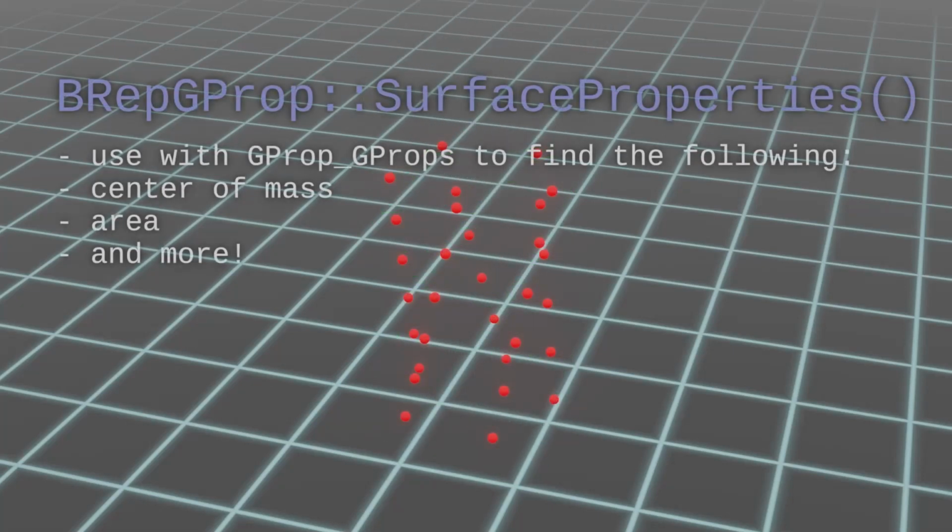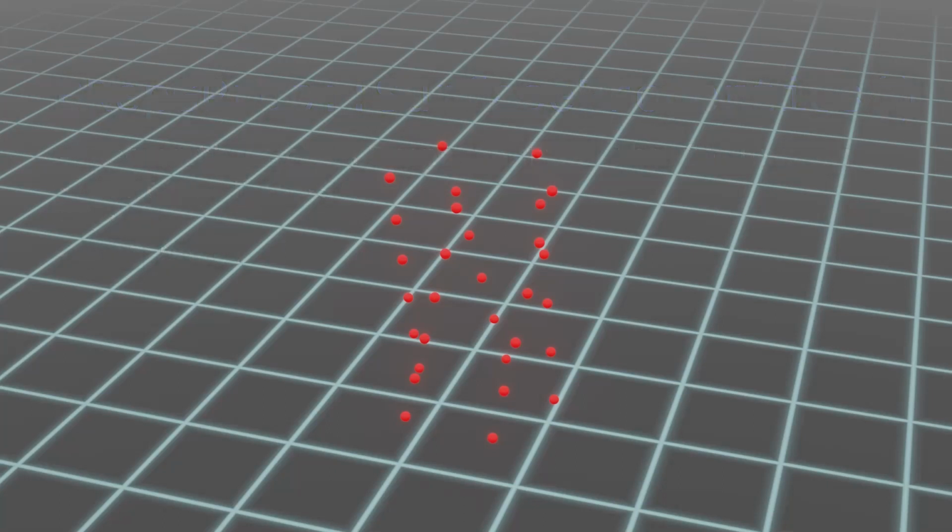I'm using another useful component of the library here, the geometry properties. This allows you to do things like find the center of mass, which is what I'm doing here, or you can use it for the area of a face, the volume of a solid, etc. So that's what I do here, and then I connect these center of mass points, making a polygon, which I then convert to a face.